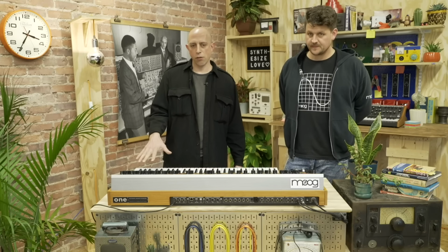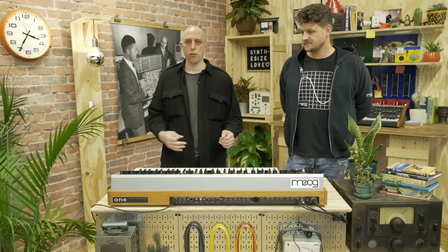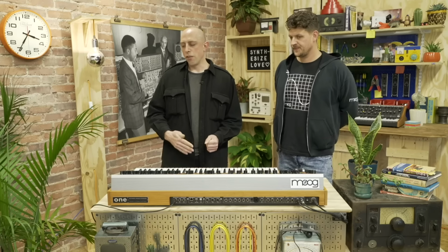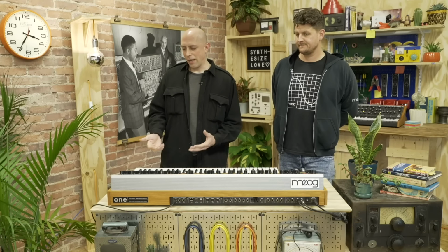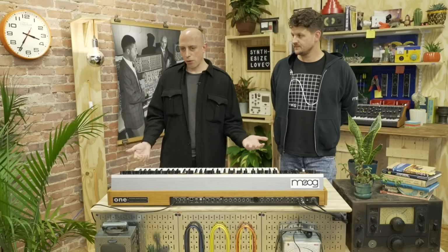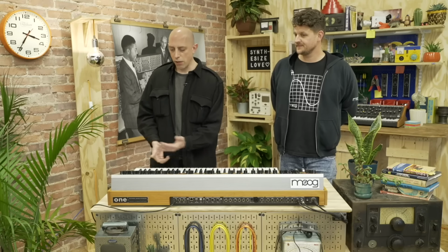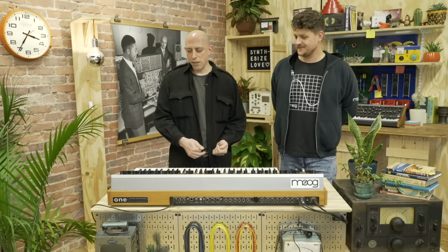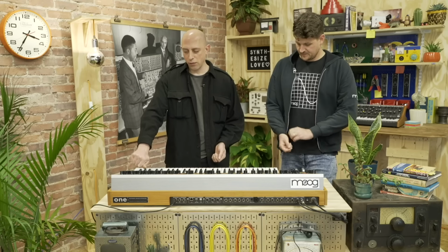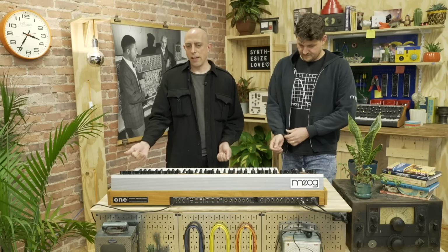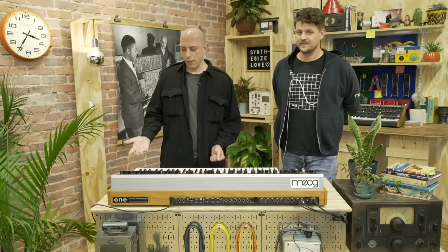The master effects are on a send bus, just like the aux sends on your mixer. And so the dry part of the signal, if you're talking about the master effects, is 100% analog straight to the outputs. And only the part that you're sending to the effects bus goes through A to D conversion.